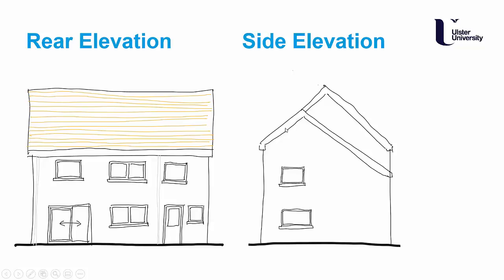The side elevation helps us appreciate things a little bit better with two different roof levels. On the rear elevation here we have the fascia board, and then we have the barge board on the side elevations, and then the walls shown in position. One other very important aspect is to think of ground level and making sure that you have it clearly shown. However, it's probable that you should also include a little bit of a distance between where the door is and the outside ground level.